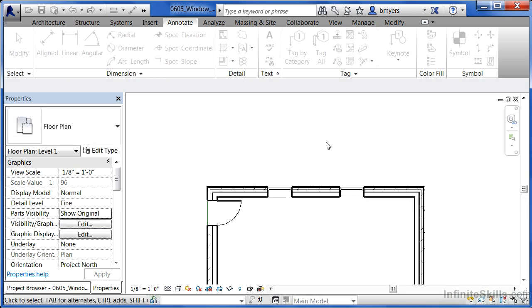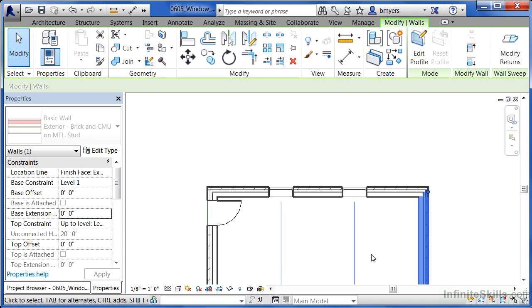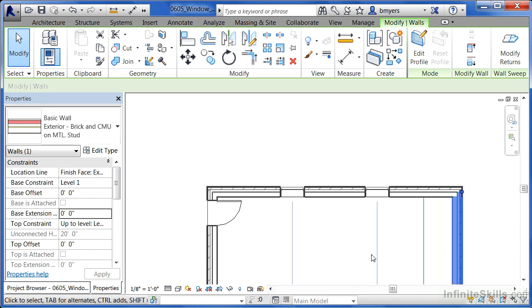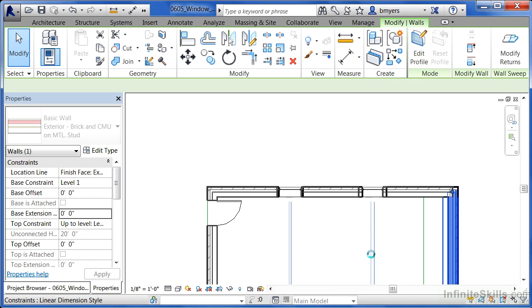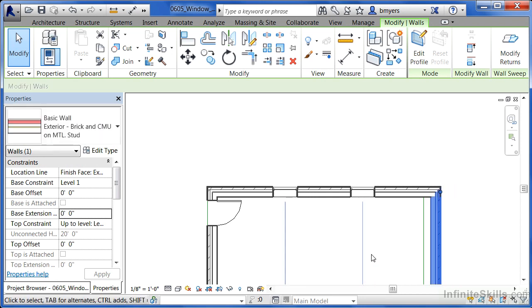What the warning message was saying is that even though the dimension is gone, these windows are going to continue to be equal no matter what happens to our drawing, whatever happens to our building. What this means is if you select this outer wall here, now look at your keyboard and click the right arrow key. If you start tapping the right arrow key, it's going to nudge that wall over to a different location. But as you nudge that wall over, the window stays centered along whatever the length of that wall is. Go to the left again, it'll do the same thing.